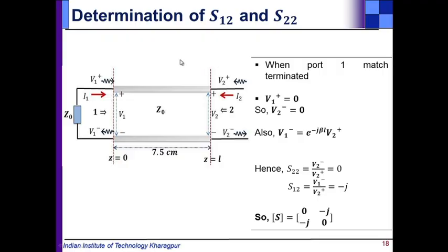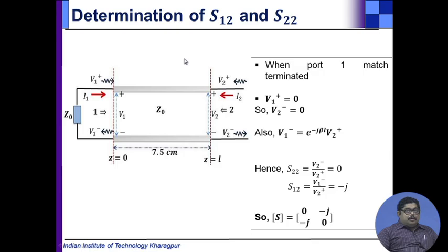Now, if you were asked to find the z parameter of that, then you can use the formula we have given to go from S parameter to z parameter, but directly evaluating the S parameter is easier, because this is a distributed line. Here the wave picture is more prominent or more explicit, you can say. That is all. This type of problems as a microwave engineer you need to solve, to find S parameters of various circuits, networks, etc., and for measurement, your help is the network analyzer.